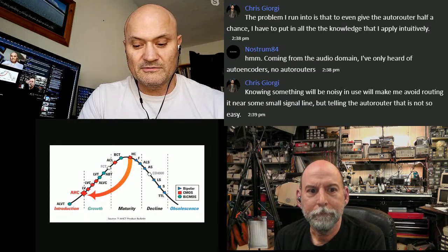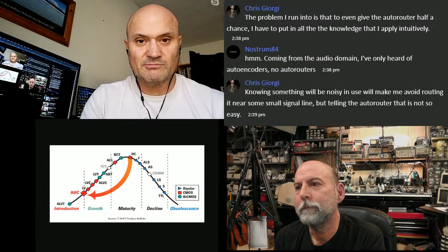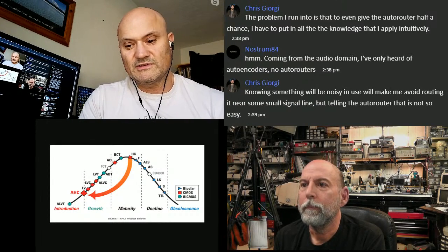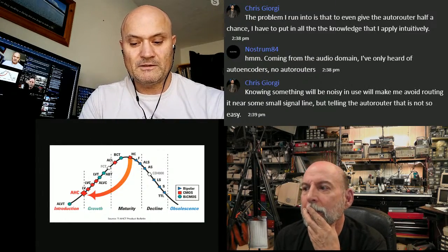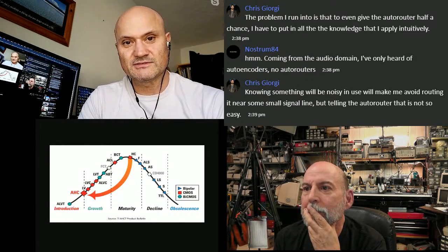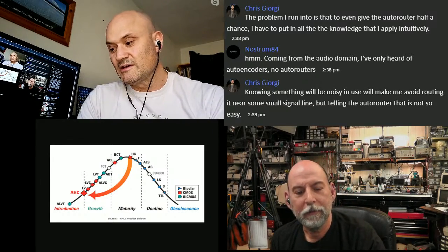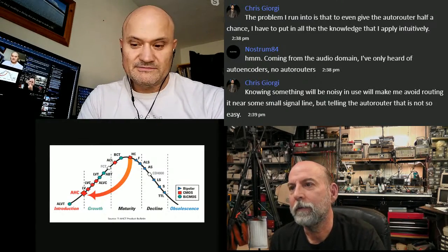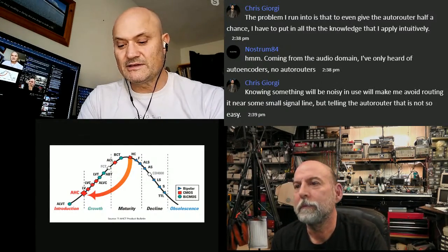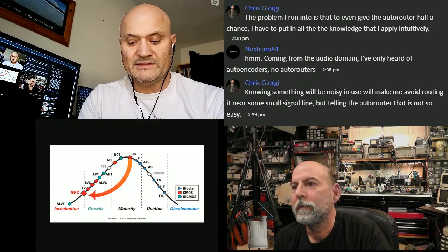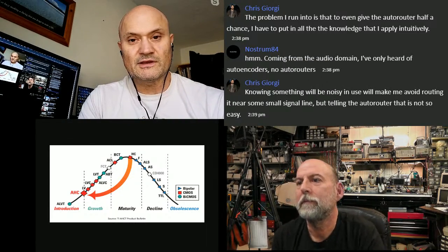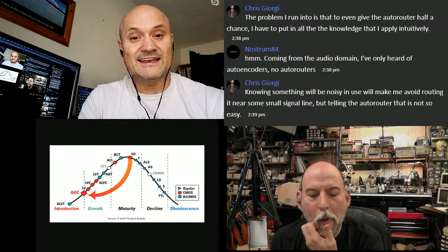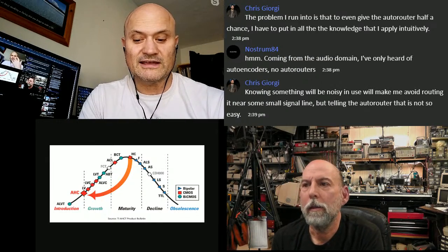If you want it to keep things spread, you just cycle through the modes and use push and shove, but don't use hug and push, or use walk around. Walk around's kind of similar, and this is the same in Eagle, which has these different modes, and I guess any PCB CAD worth its salt has this capability.